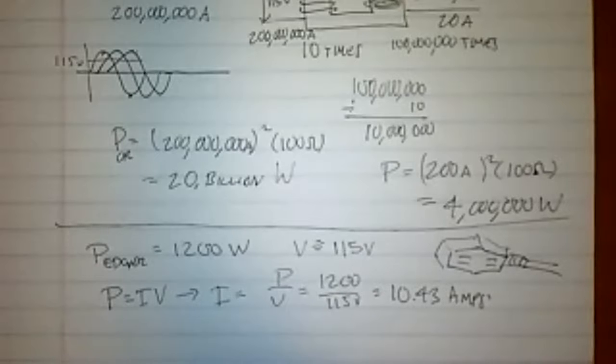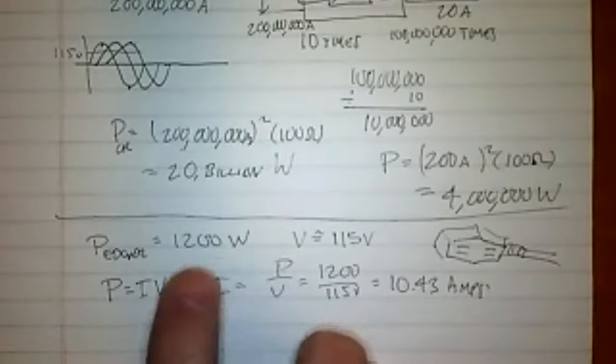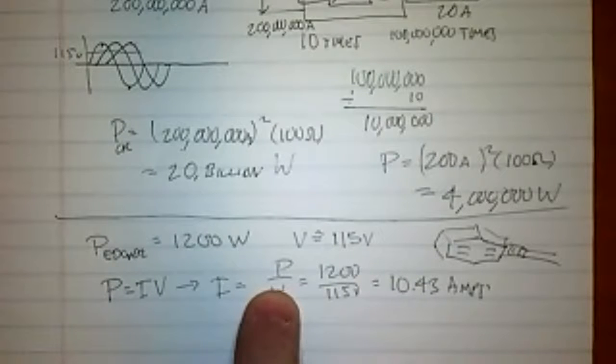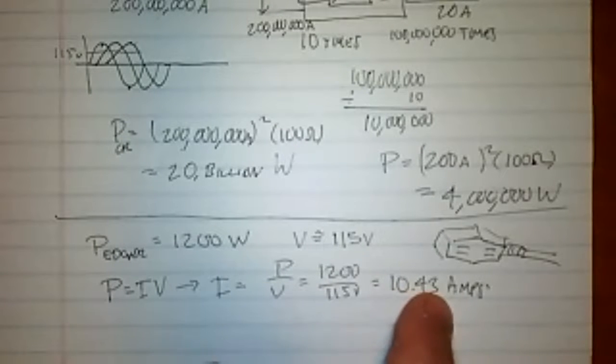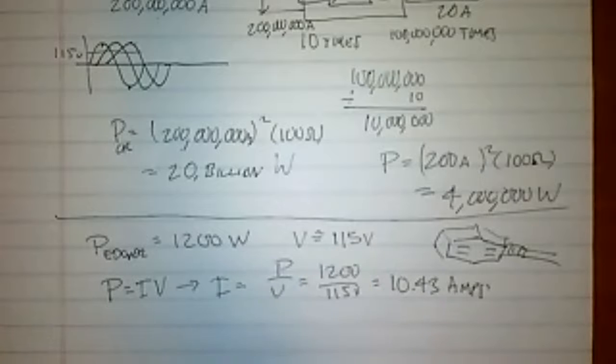Then everybody wires it that way. A building inspector comes behind you, checks the gauge of the wires you're using to connect the receptacles to one another, checks the grounds, makes sure everything's connected properly, all that good stuff. You can use P equals IV and just assume the voltage is 115. Notice if the voltage was 120, you would get a lower current. So it's better to use the low voltage, the safe side, when you're trying to estimate the current, just in case the voltage does go that low. You will know the maximum current to expect. So that's kind of useful.